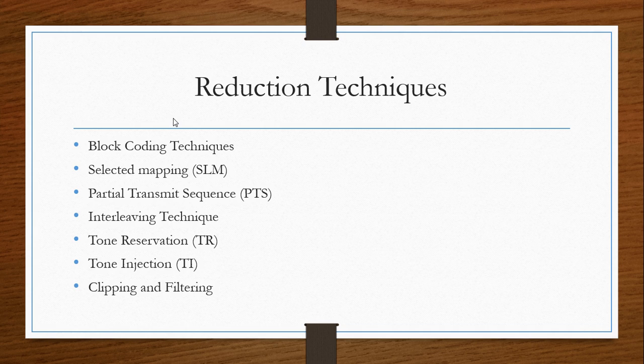Adaptive interleaving sets up an initial terminating threshold. It stops once the PAPR value goes below the threshold, rather than seeking all interleave sequences. A minimal threshold will compel the adaptive interleaving to look for all the interleave sequences. The main importance of the scheme is that it is less complex than the partial transmit sequence technique, which will be discussed in a short while, but obtains comparable results.